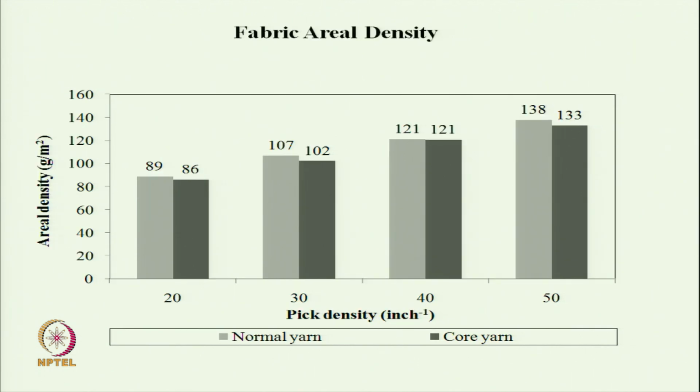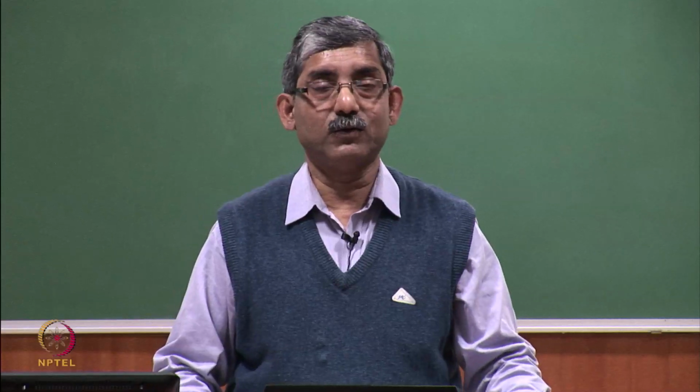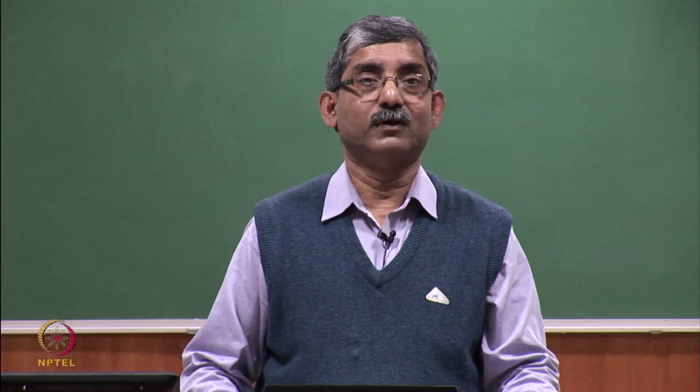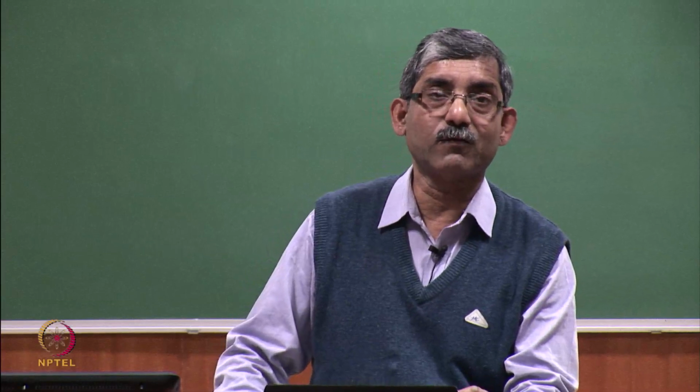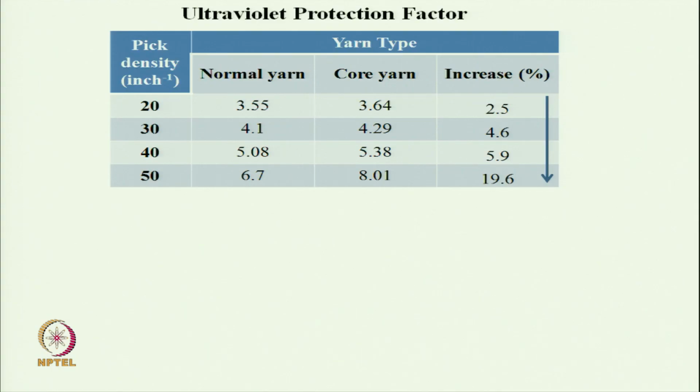If we see, the areal density is almost the same for both the cases. So, by yarn engineering we have created different cover factor but the same mass per unit area. We wanted to see whether the effect of mass per unit area is significant or the effect of cover factor is significant. Here we can see, for different pick densities, the proportion of increase in cover factors is reported.